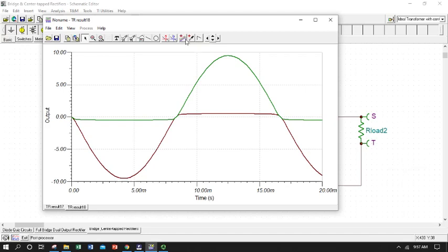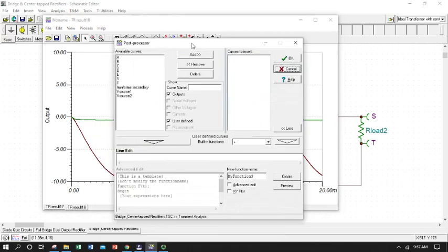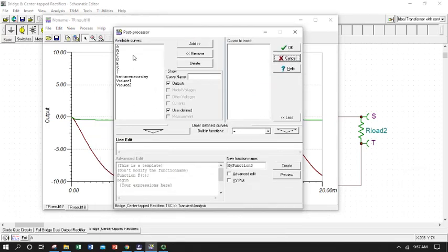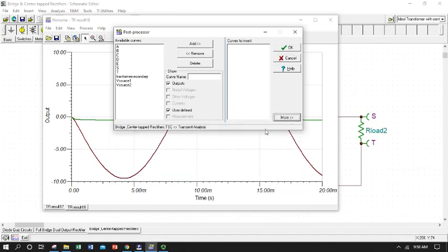And this is a handy tool when we want to get differences in node voltage points. So it's this bunch of waves, little push button. So we push it. And it can be fussy. Sometimes it will run into an error and not want to subtract things.